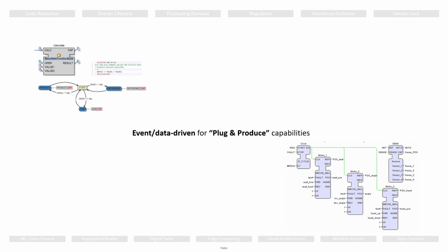This means that function blocks are triggered by specific events, such as a sensor detecting a change, the start of equipment, or even an operator action, rather than being continuously scanned. This event-driven approach aligns much more closely with the IT world, where most computer systems and software applications operate event-based. Think about your Excel sheet. It doesn't continuously refresh every piece of data. It reacts when an associated cell is updated, or even with a refresh request. This is similar to how an IEC 61499 control system reacts when an event occurs.